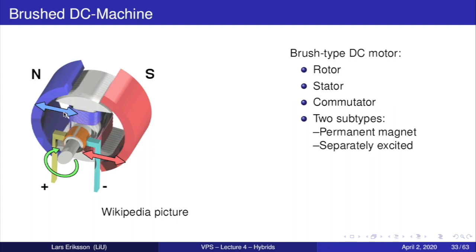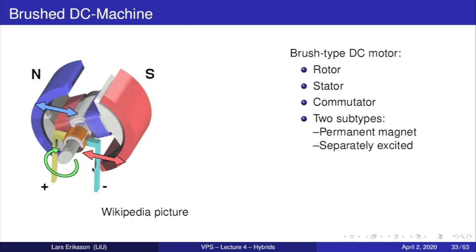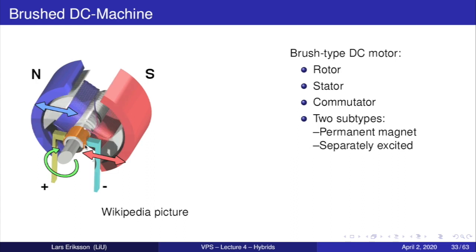And the repelling forces continue here, and they are still continuing here, and we also have now pulling forces here that are trying to align the rotor to the field inside the machine. Here you see that we're about to switch polarity as we're doing now, and then the current reverses in the coils and we get the polarity here, so the cycle starts again.